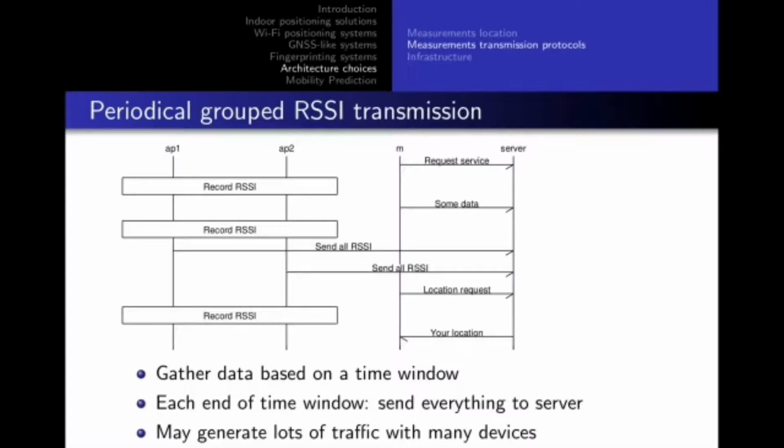Then we have another solution, which is the periodical grouped RSSI transmission. It's based on gathering data based on a time window. So here we have the mobile device. It requests a service, it sends some data, and all the access points within range will record the RSSI and store them in their memory.